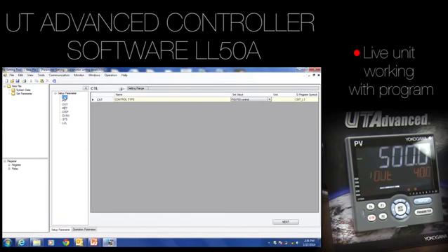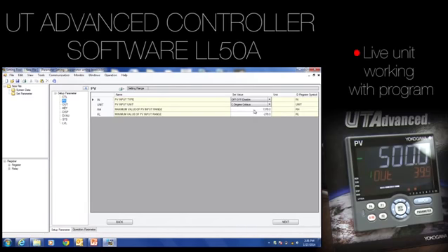In this case, control type. As you remember before, there were about 7 or 8 parameters here. In this case, I can know what I'm doing: PID, batch, feed forward. I just select the mode that I want and away I go. PV, units, input type, and the range. And again, this is really all you're going to need for your very basic control.